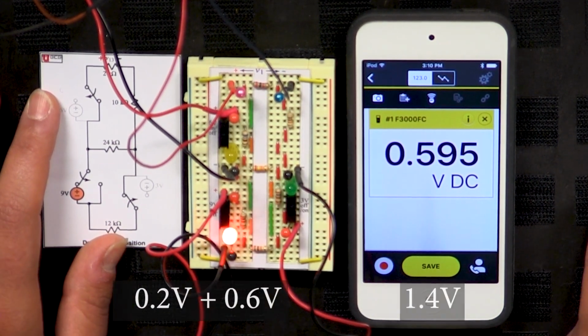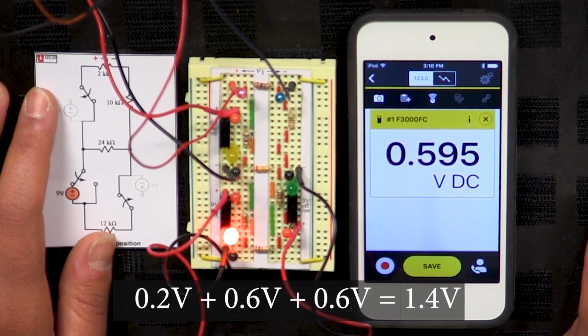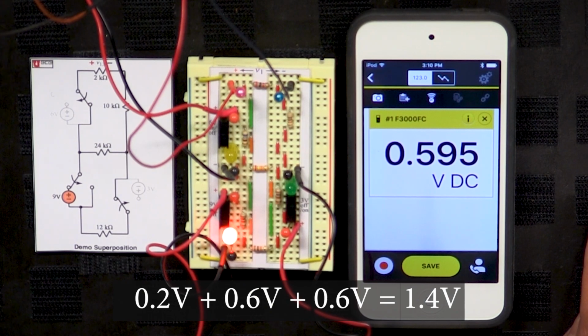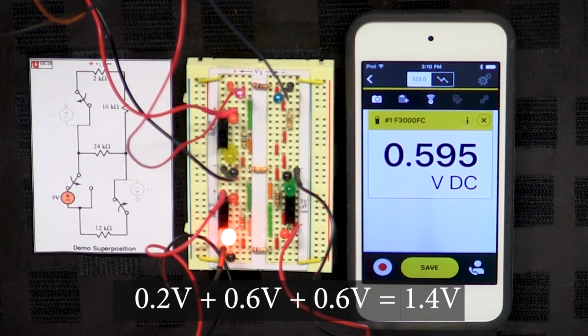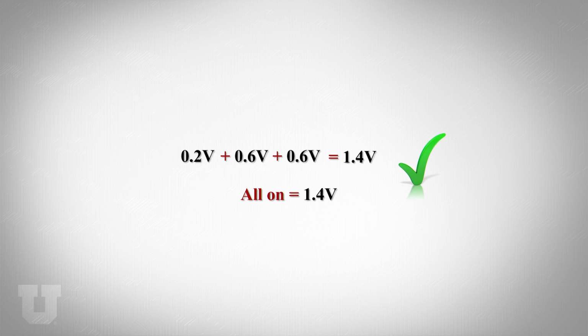Turn it on. We get again close to 0.6 volts, and we sum them up, 0.2 plus 0.6 plus 0.6, which is equal to 1.4. That's great. So it seems that superposition works here, and the total response of all the independent sources when they are acting together is the same as the summation of each individual source when acting alone.